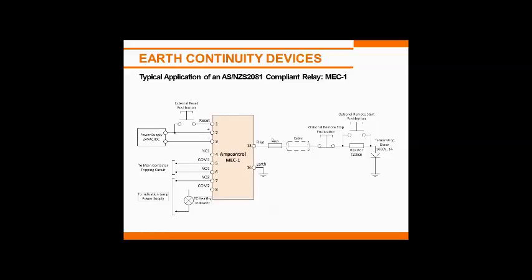So in most cases we recommend a fuse of some type, just in case there's a fault in the cable and high voltage is connected to this point. There are other protections, but a fuse is recommended. A remote stop is usually just a button along the pilot lead, which trips the relay fairly quickly. And here's the remote start condition. It's a 100 ohm resistor with a switch put across the resistor, so that the relay sits in an off or non-operating condition when it's asked for a remote start condition.